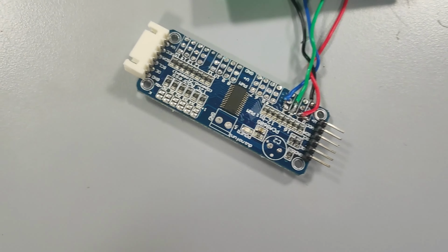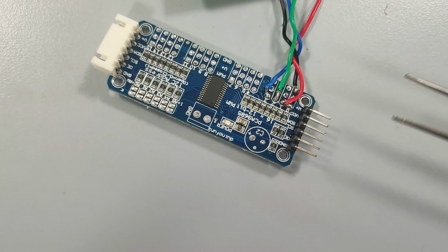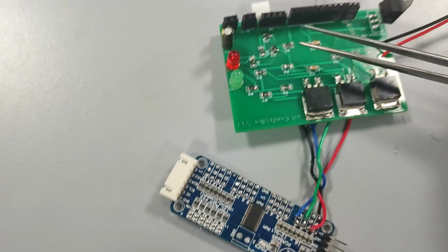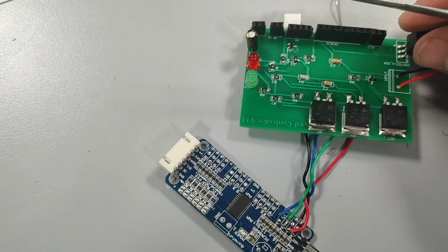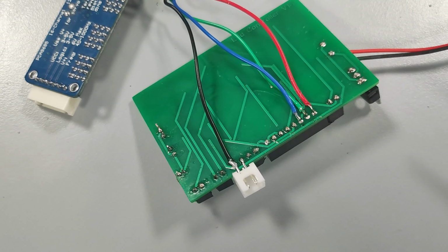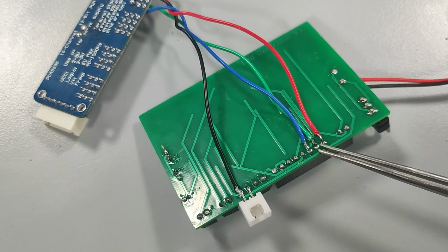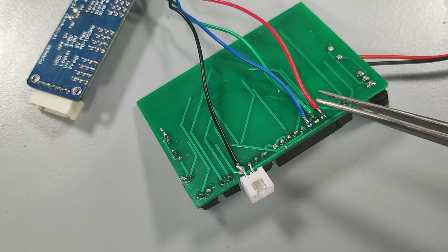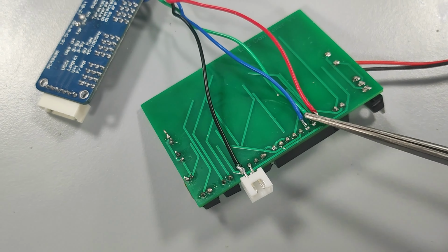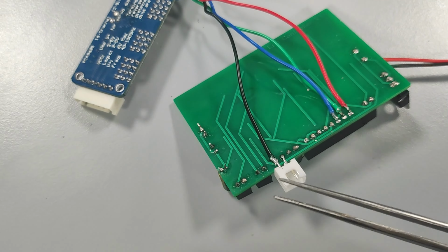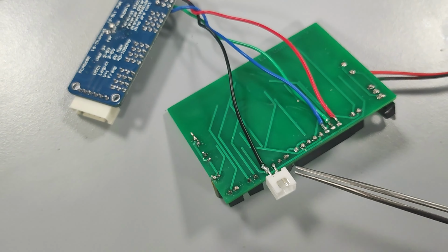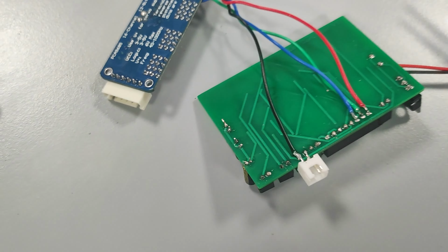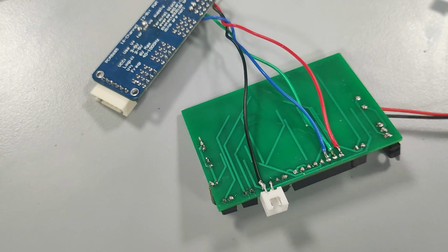The initial idea was for it to consist of 3 boards: a microcontroller, a PCA chip, and an amplifier board that will send signals to the LED strip. However, this idea was not really good in realization. When I soldered everything together, it was really flimsy, with too many wires. You can make many mistakes while soldering them. So I decided to make one board that will have one microcontroller and just do its thing.